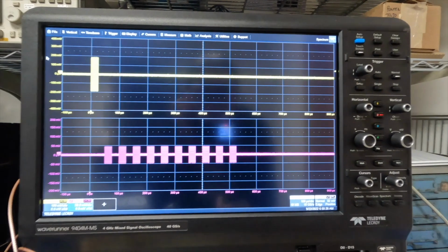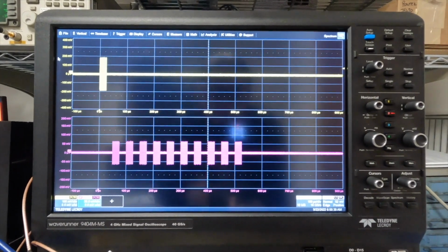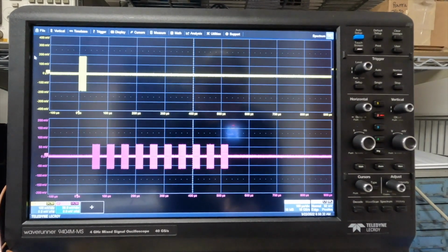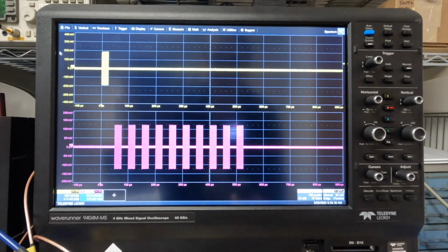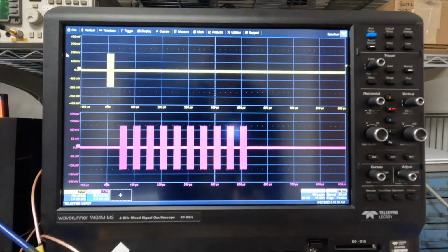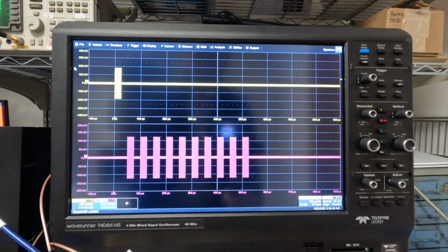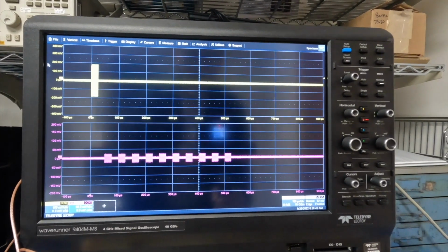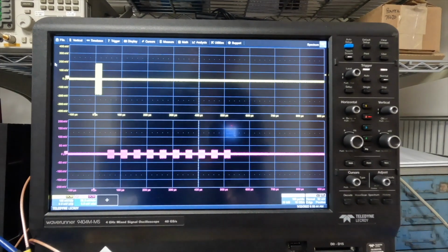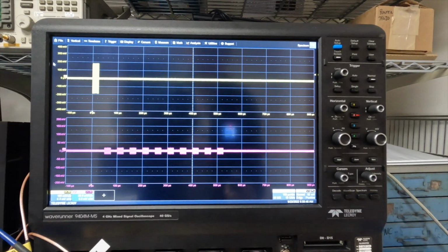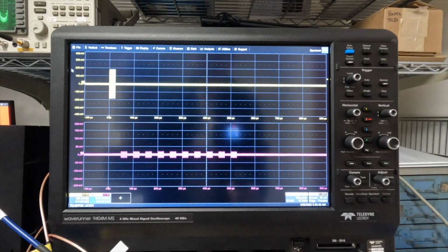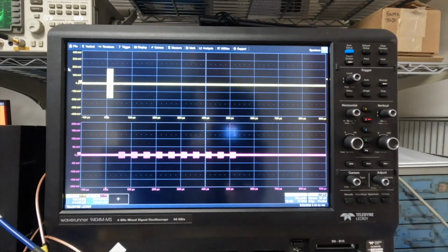And we're going to go to 6 dB higher than the normal zeroed output, and here's a full 12 dB higher than the normal output. And we could also go negative, so negative 3 dB and negative 6 dB, depending on what we really want to do when we're trying to fool the victim radar.